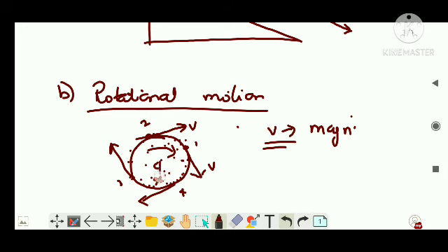It is at a lower distance from the center, that is, r is less. So r is less means, with V equal to r omega, when r reduces, V also reduces. So the particle which is here will have lower velocity. Again, a particle which is here will have lower velocity. That means a particle at the center will have zero velocity. So each particle, depending upon its position on the rotating disk, has different velocities as well as different directions.